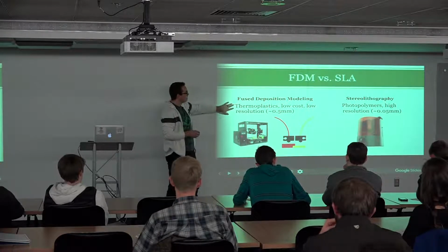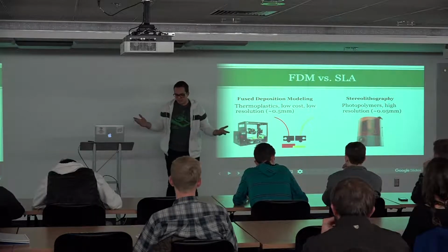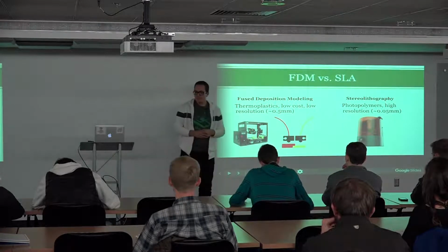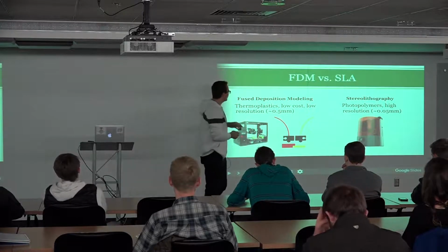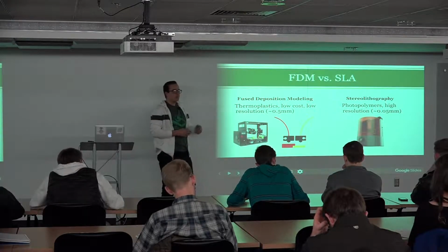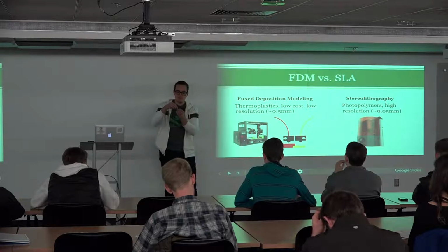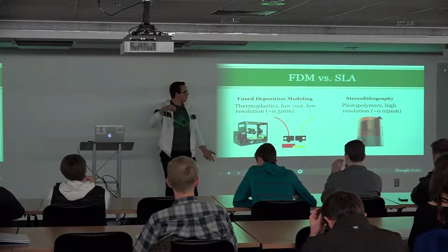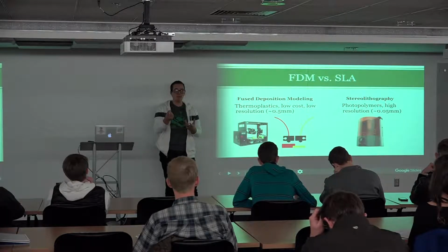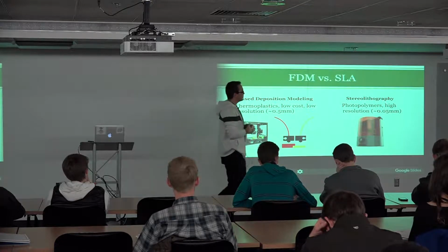Generally, lower cost because the materials are really cheap. You know, Legos are made out of thermoplastics. There's thermoplastics everywhere. This power strip has a thermoplastic molded casing on it. So it's just a very low cost way to do 3D printing. But it is relatively low resolution compared to some other methods. The machines we use have a nozzle of about 0.5 millimeters, so any feature in your model that's smaller than 0.5 millimeters probably won't come out, because it's just not high resolution enough for that.